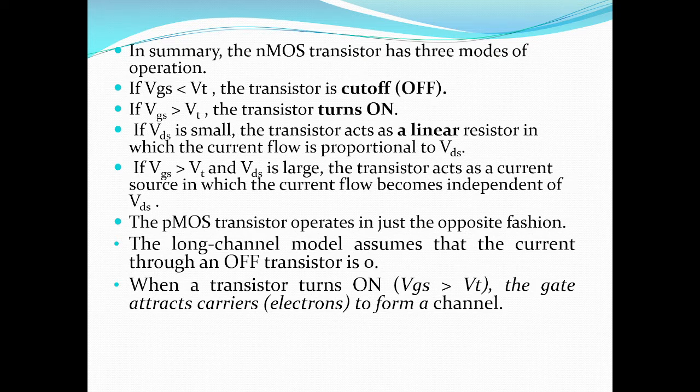Next, the PMOS transistor operates in just the opposite fashion. The long channel model assumes the current through an off transistor is 0. When a transistor turns on, that is, VGS is greater than VT, the gate attracts carriers to form a channel.